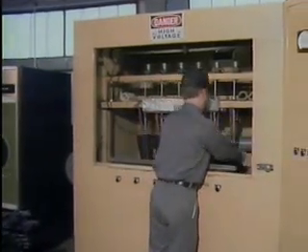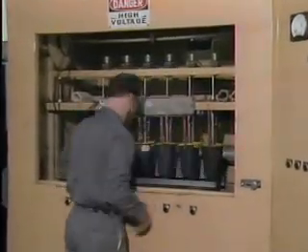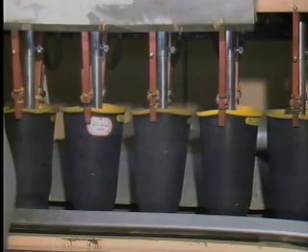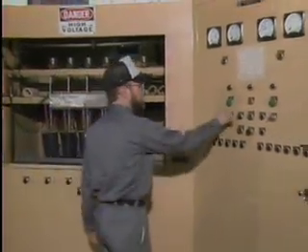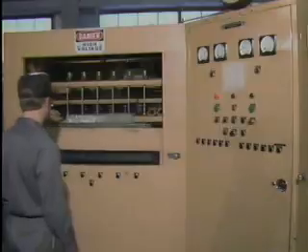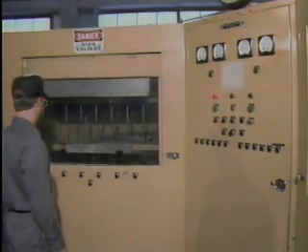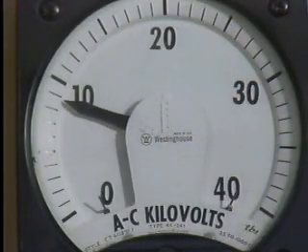This is a test apparatus that's used to perform dielectric tests on insulating gear. The apparatus can test 6 gloves at a time. Each glove that's being tested is first filled with water and then lowered into a water-filled tank in the apparatus, which is connected to ground. A hot lead then applies the test voltage to the water inside the gloves. The technician monitors the test by watching a current meter to be sure the leakage current through the gloves remains